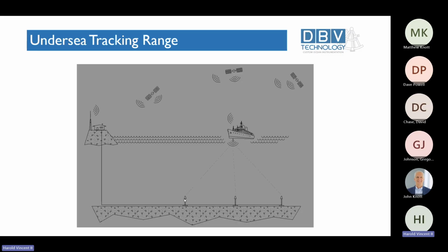After that's done, and after these hydrophone positions have been determined, then a submarine or a torpedo or an underwater vehicle that's equipped with a pinger can transit through this area, transmitting an acoustic signal. That acoustic signal is received at these hydrophones at known locations, detected by signal processing equipment on shore, and the positions of those underwater vehicles are obtained. And you're able to get positions constantly and hence track the undersea vehicles.